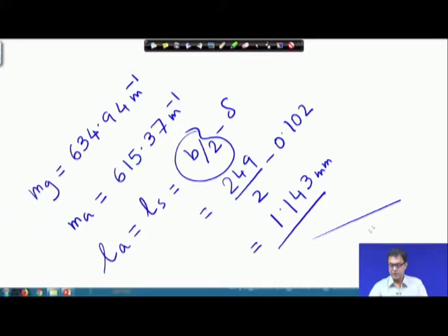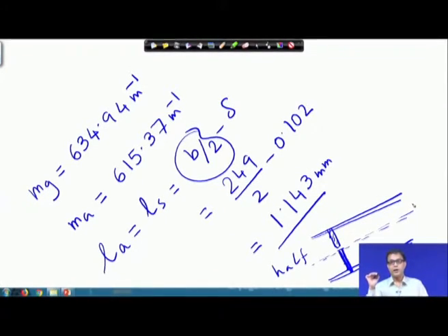If you remember, in some of the previous classes we talked about the half fin idealization, where half of the fin is as if attached to this plate and half of the fin is as if attached to the upper plate, and thereby this half factor is coming, as if an adiabatic plane is there at the middle.